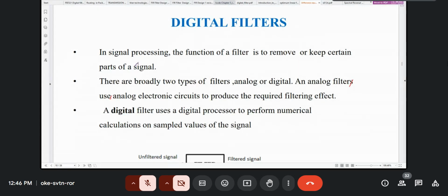It can be a bandpass filter, like a signal has passed through a system, and therefore it has noise. And you know, noise has got a constant power spectral density. So you may want to remove what is outside, because noise has a constant power spectral density, and you don't want to carry that power. You don't want to process that power or carry it to the next section. So for example, you use a BPF filter, but you filter whatever is outside the band of interest.